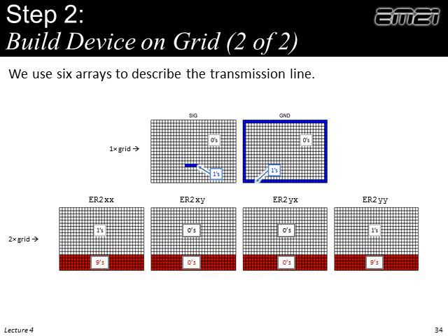And we get a little bit of asymmetry just in our boundary conditions there. So the fields around the transmission line tend to look like they're getting sucked towards one side or the other just due to that asymmetry. If those boundaries are far enough away, it's really not that big of a deal. I just like to put this in so things look symmetric and they look prettier, but it's actually not needed. And it does not improve the accuracy, it's just the answer looks a little bit prettier. So we could leave all zeros along the left, top, and right sides here, but we definitely need ones along the bottom as our ground plane.